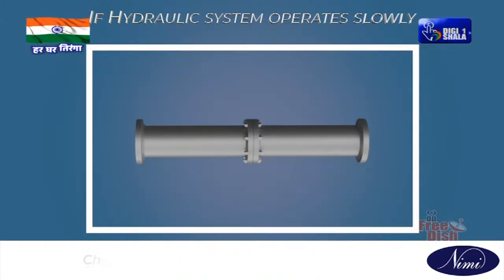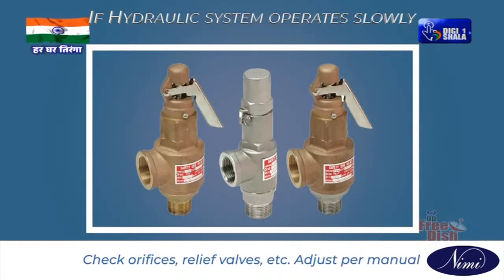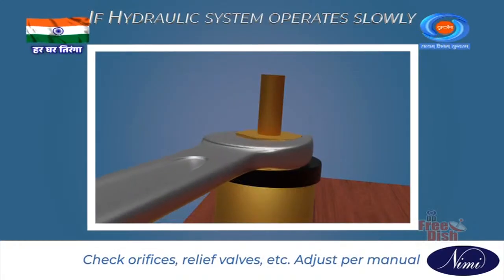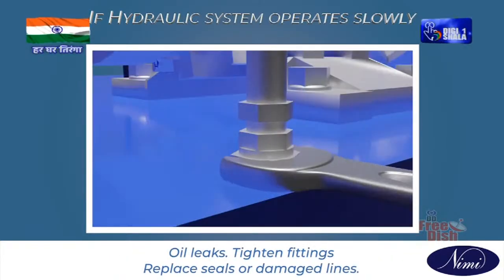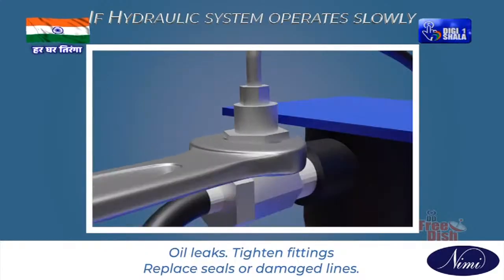Improper adjustments: check orifices, relief valves, etc. Adjust per manual. Oil leaks: tighten fittings. Replace seals or damaged lines.